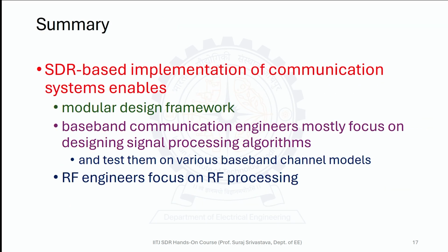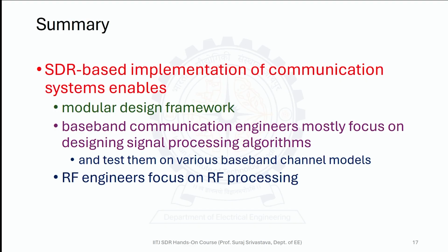Now, let us see the summary of this discussion. As we discussed, SDR based implementation of communication system enables a modular design framework, because the baseband communication engineer and RF engineer can work independently during the initial phase. The baseband communication engineers can mostly focus on designing the signal processing algorithms and test them on various baseband channel models, whereas RF engineers can focus on the RF processing, basically how efficiently to convert the baseband signal to electromagnetic waves.